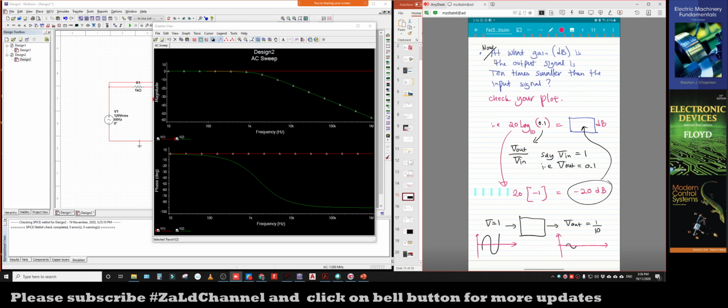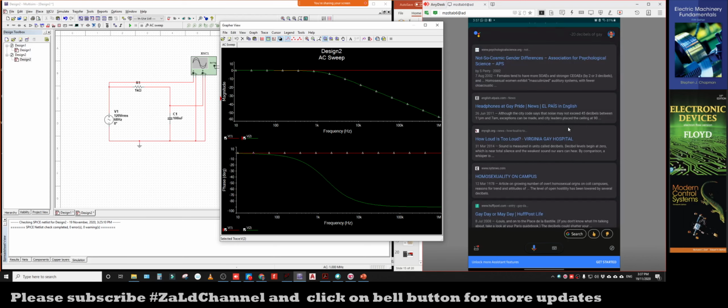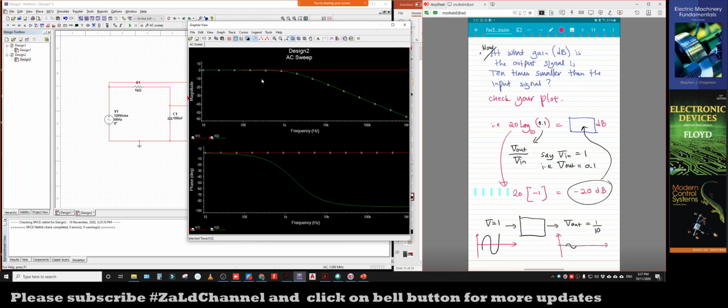To answer this, what gain is the output signal 10 times smaller than the input signal? 10 times smaller means negative 20 decibel of gain. Meaning that we have the filter circuit here, and then we plot this circuit like this. If we try to trace the negative 20 decibel, it will go somewhere around this point.